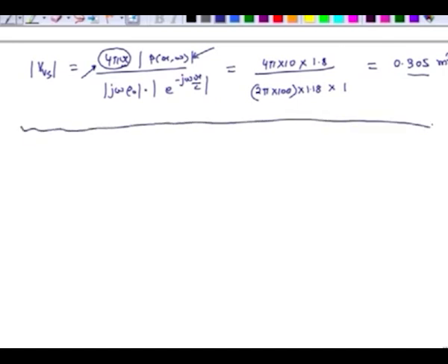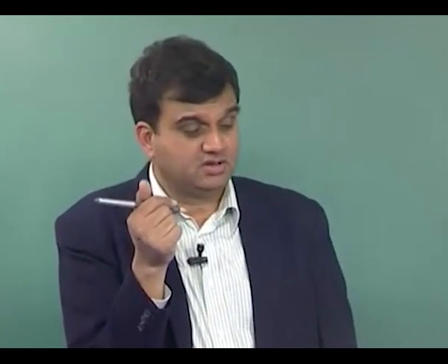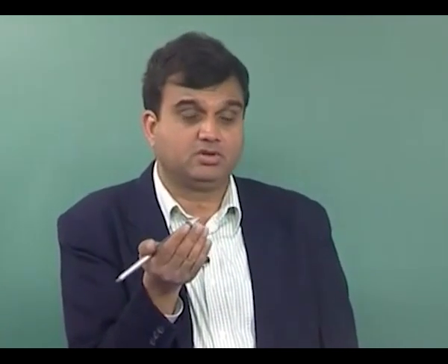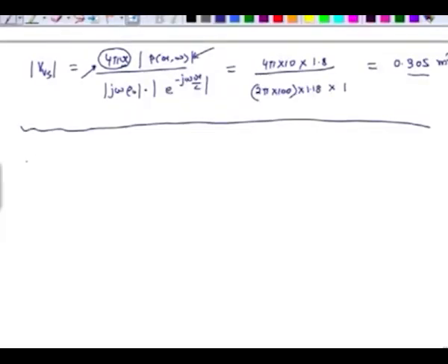So, having said that, we will continue understanding this particular source which is emitting 5 watts of power at 100 hertz, and our next step is to figure out the value of I, that is intensity in decibels, the value of sound pressure level in decibels, and the magnitude of velocity displacement. So, what we are going to find out is I in decibels.